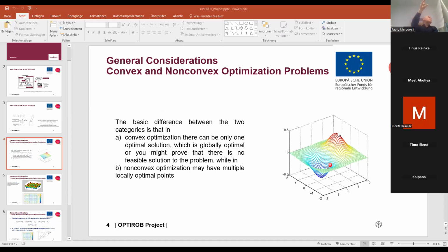If you consider the cost function, force divided by volume, parameterized by all dimensions, number of windings, permanent magnets, in this case we are looking for the maximum: maximal force, minimal volume. This cost function, the ratio between force and volume, we look for the maximum. But if I consider the inversion, volume divided by force, we are looking for the minimum. This means maximum and minimum could be represented with the same optimization problem in this sense.